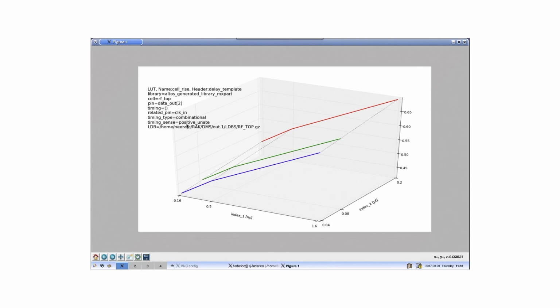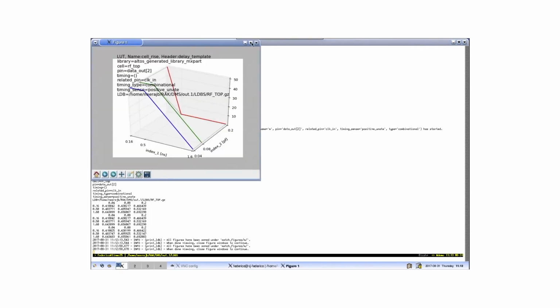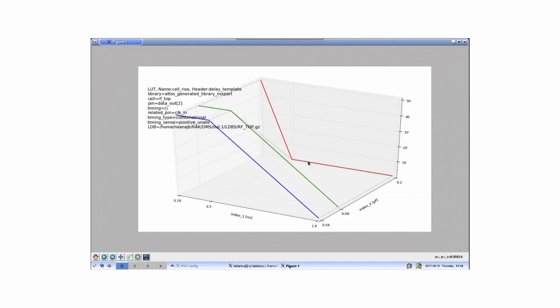On the axes, you see the input slews and output loads, and this is the behavior that you would like to see, obviously, in characterized data, where values are monotonically increasing with slews and load. After we do the modification of adding a very large number to those entries that satisfy a specific condition, and redisplay that data, you'll see, obviously, that change showing up as a big discontinuity in the curve. That concludes my presentation. Thank you for your attention.